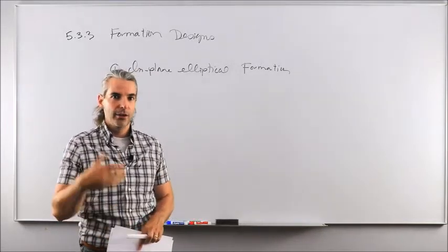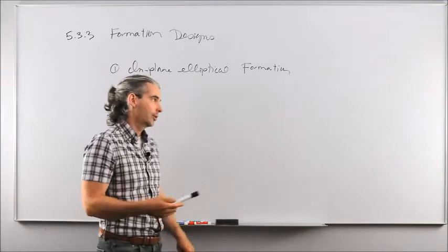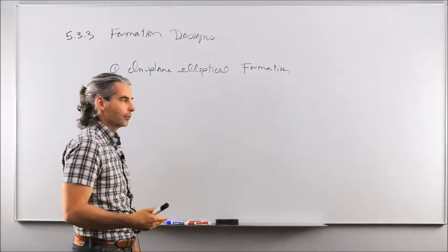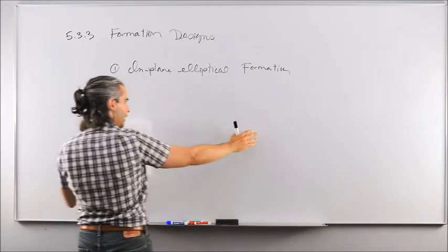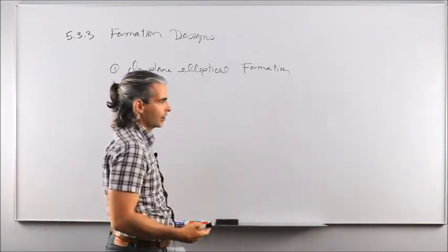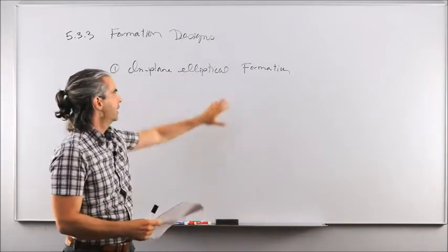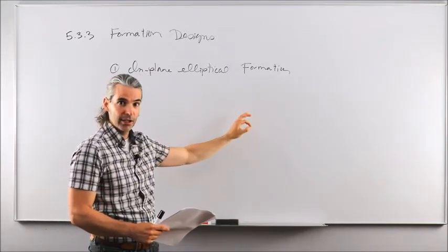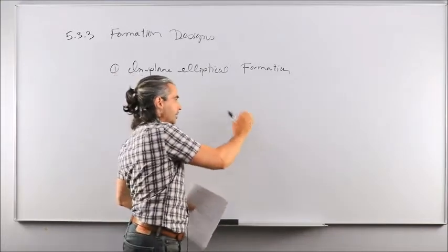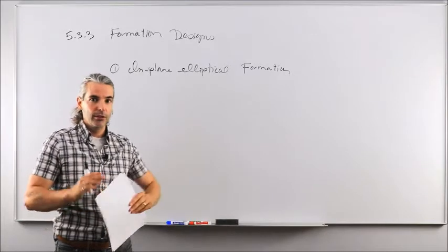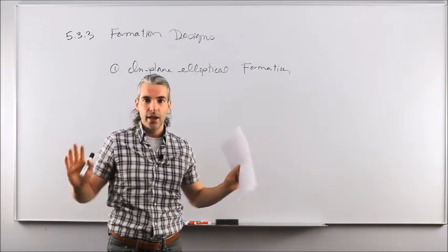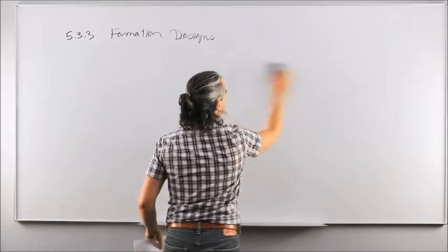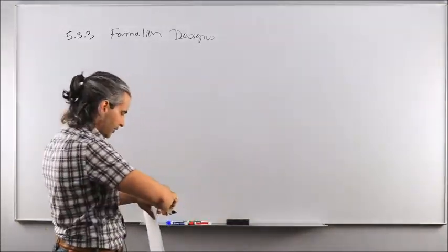We design control systems that are intelligent and adaptive and smart enough to make sure that the relative motion stays bounded through active control or through propulsive maneuvers, regardless of perturbations that would naturally tend to make both spacecraft drift apart, regardless of what you choose for the initial conditions, okay? But here, for the purpose of this course, we are assuming that just placing the chaser spacecraft at a specific location initially with respect to the target and pushing it with some initial velocity with respect to the target in whatever direction is sufficient to generate passively, or hands-off, a given formation. Okay, close the parentheses. So that was the first formation design achieved by careful selection of initial conditions.